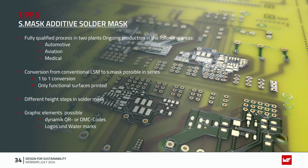So to sum up, the S-mask additive solder mask is a fully qualified process. We have it in two production plants in Germany. We have ongoing production in the automotive area, aviation area, and medical applications, which, as you know, are not the easiest areas, but it works very well here. It has a lot of advantages. If you want, you can change your board tomorrow, either by a one-to-one conversion. You just send us your Gerber files, and we can create a drop-in replacement and print the solder mask as you have it today.